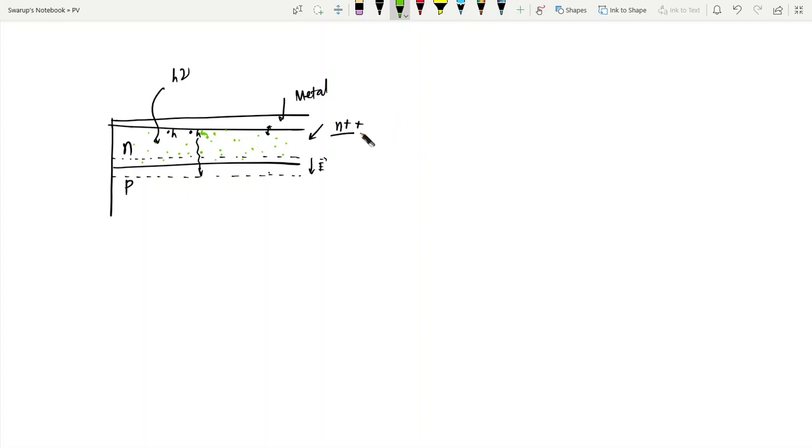So just because we want to reduce this metal semiconductor barrier height, we cannot simply increase the doping concentration. Then we are losing holes, because the diffusion length of holes, LH, will reduce. The effective diffusion length of holes will reduce as we increase this doping concentration, right.